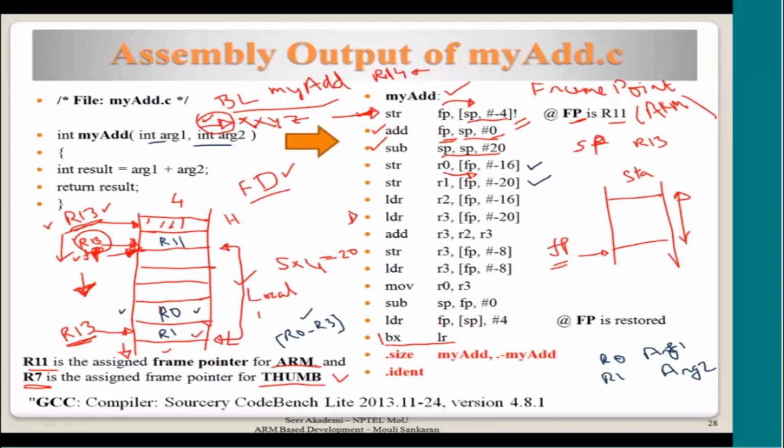And then it is load, LDR. Now again this value is copied. So 16 is copied to R2 from this. So actually it is writing into this and then copying from here. So you may see that it's not optimized code. Unless you mention some optimization, the compiler is not free to do any optimization. So it does according to whatever we want, because that's why I will be able to explain what is happening. Okay, so I have not put any optimization, so it is not doing any optimization.